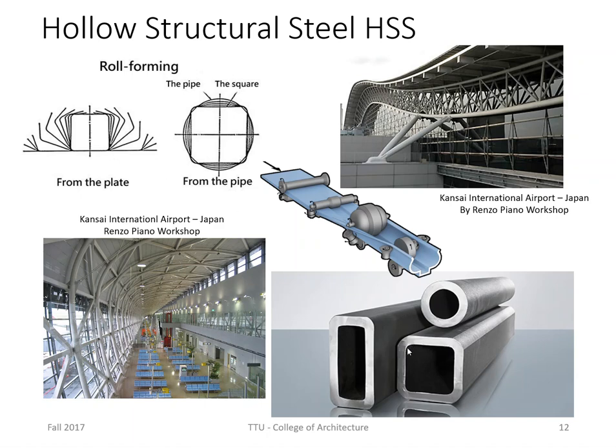In the case of the square HSS, it's called HSS because it's hollow structural steel, right? This is gotten by folding, running it through rollers that slowly begin to fold. It folds this edge up, then it starts to fold this edge up until it closes here. And when it closes here, that closure is then sealed off with a welding joint. It's welded and then of course sanded down and buffed, so it may have a really nice finish that can then just be painted.